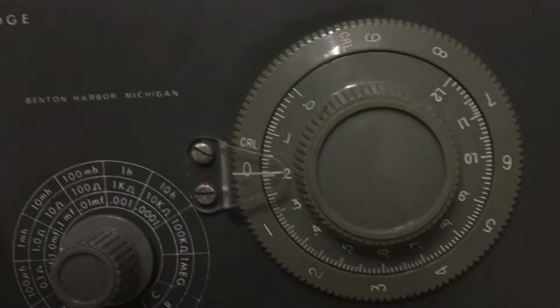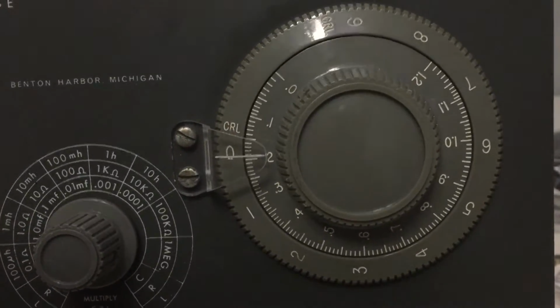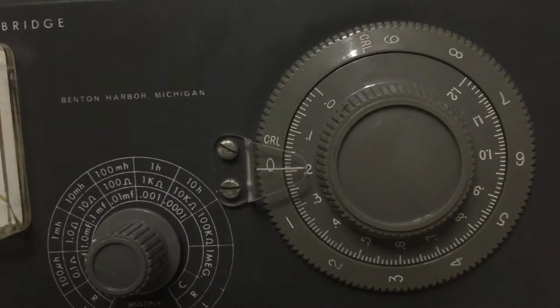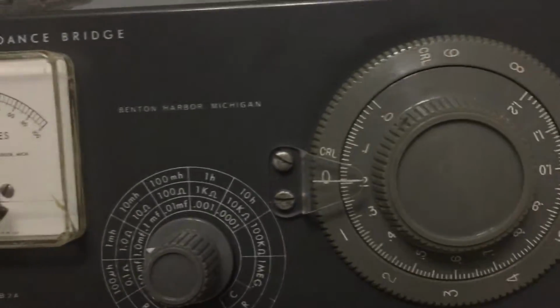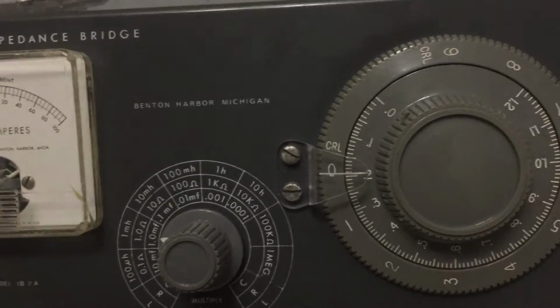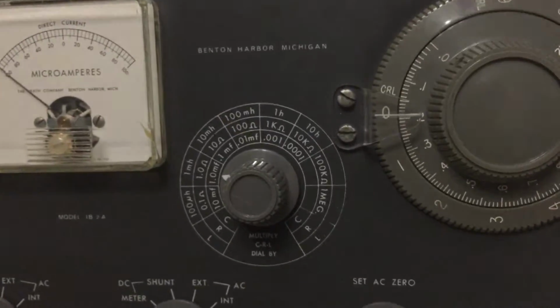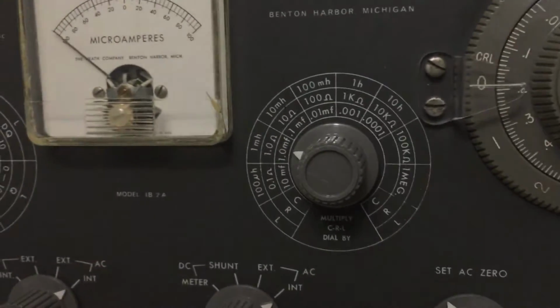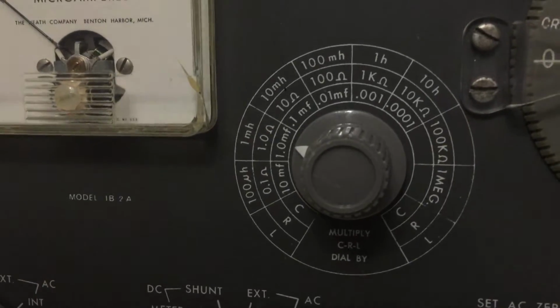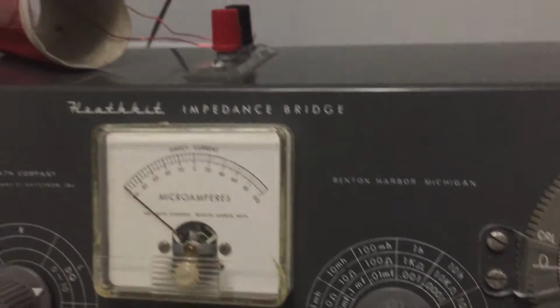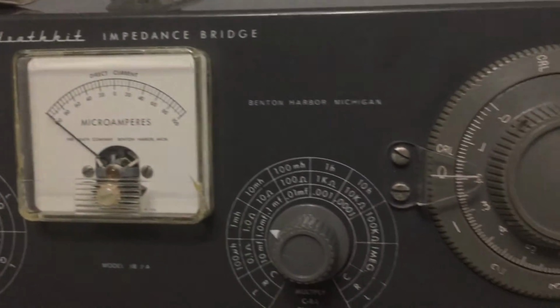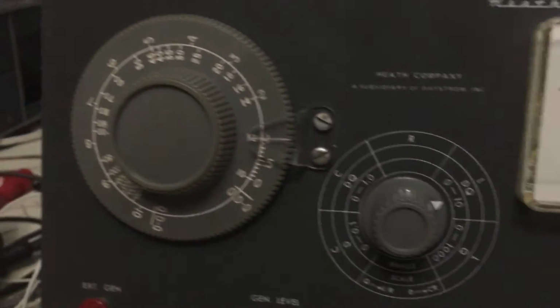Giving us obviously less resolution than the other one, but effectively 0.19 millihenries of inductance, which comes very close to the 0.192 that I got from the digital meter. On the other resolution, using the 100 microhenries, we did find that this actually read 0.199. Obviously, you really can't see the 0.199 on this one, but this is how we measure inductance on here.